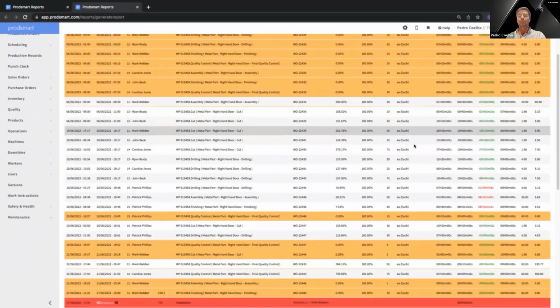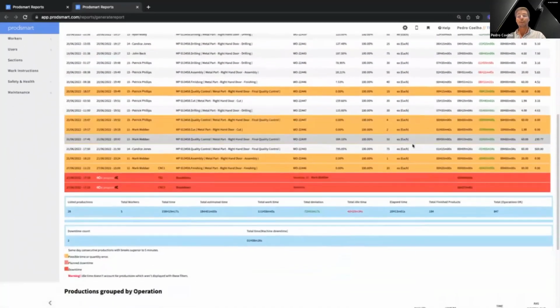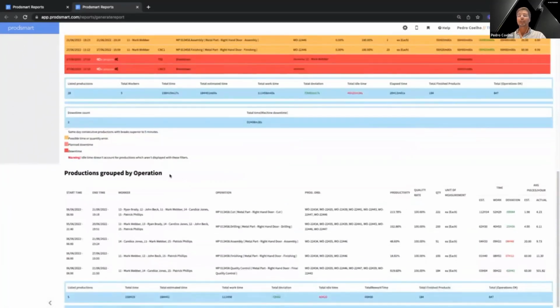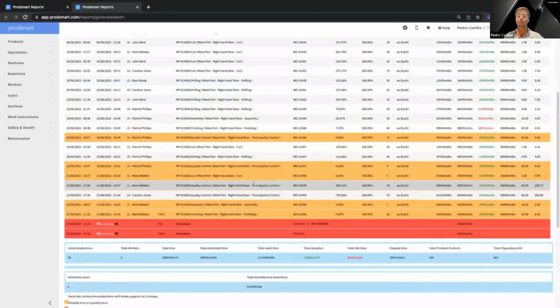At the bottom of the report, you can get a summary of the production data by operation that will enable you to understand the process and where your bottleneck is. By comparing the different throughput rates, which is average pieces per hour in this case, we can clearly understand our process capabilities and validate the real bottleneck of the whole process. In this case, we can see clearly the first operation is the slowest one, which is constraining your material flow.